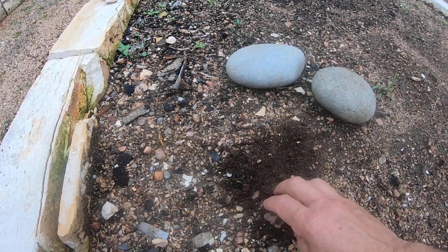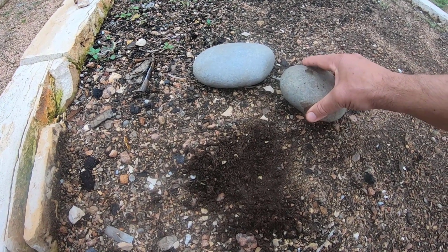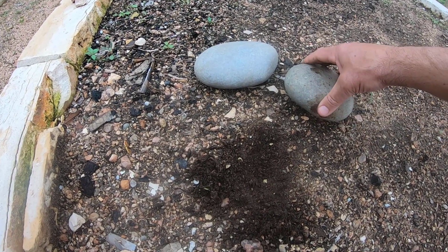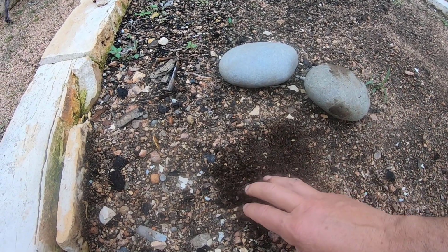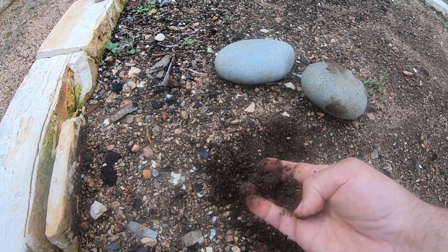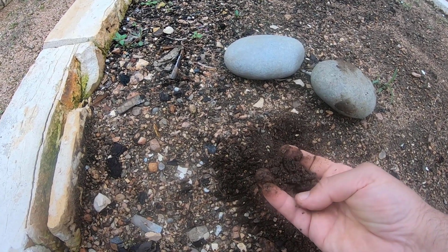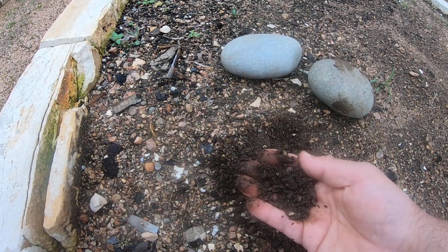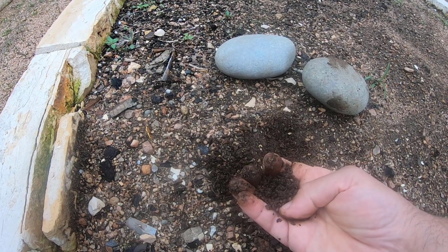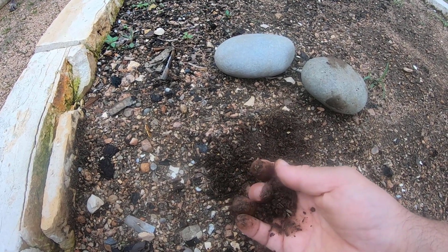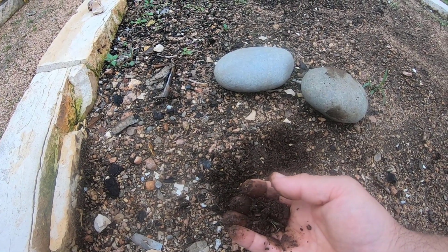And so if you take your gamma ray log over a large piece of rock like this, you will see that the values of gamma ray log will be relatively small. But as you go into the Earth's cycle of weathering, chemical or mechanical, we have more and more clay particles, and the particles become smaller and smaller. So if we look at the gamma ray log of the soil here, you will see that the values for the same volume of material will be considerably larger.